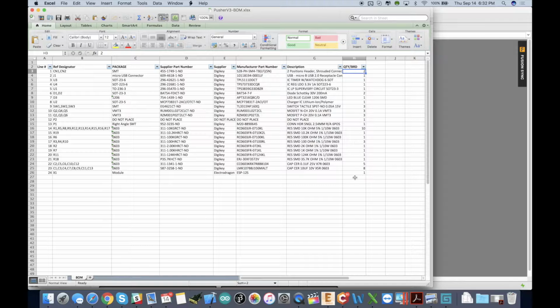board. So if you're going to order a few boards' worth, for example, I think for this board, and I'm actually going to work through the process right now. I think what I'll do is, how many boards do I want to make? Maybe 5 boards? I'll do 5. That seems a little much. I think I'm going to do 3 boards. So 3 times this cell here. And I always make a separate column for the quantity that I'm going to order. Okay, and then I resave this bill of material. And this is what I will use to upload into Digikey.